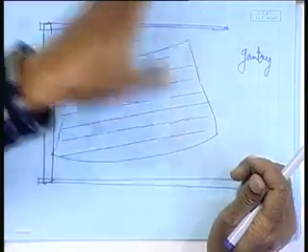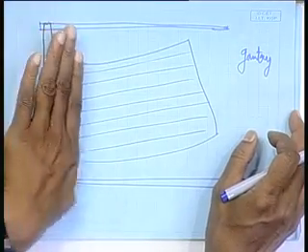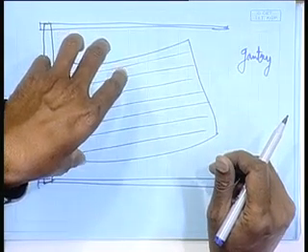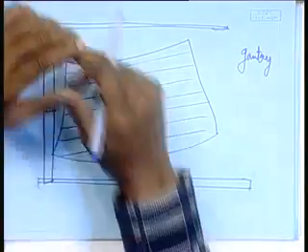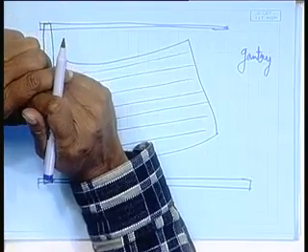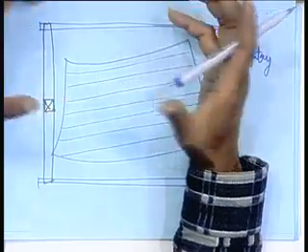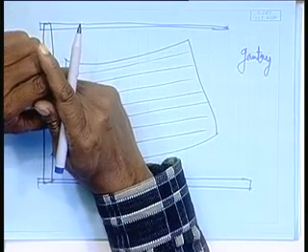But here, once all the runs of heating are given, the plate comes out, is visible, and you scan it, or use whatever monitoring device, and numerically compare with the given surface, the patch. There we will see whether it has been overbent or has remained underbent. Whatever has happened, we will check and find out what needs to be done.